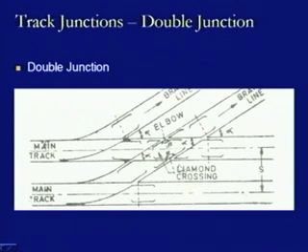So, whatever accessories or type of crossings need to be provided on a diamond crossing, that is 2 pairs of acute angle crossings and 2 pairs of obtuse angle crossings, need to be provided in a diamond crossing. So, this is acute angle, this is acute angle, this is obtuse angle, and this is obtuse angle. We have a switch here, we have a switch here, and that is how they are operated. And this is another location where a crossing will be there, or there is one crossing which is provided at this location. There are 2 extra locations where 2 more crossings will be there.